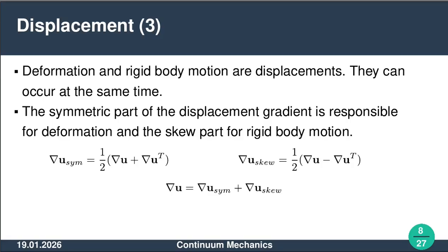The aim of continuum mechanics is to develop constitutive equations about cause and effects of a body motion, about strain and stress, etc. And for that, we need to tell rigid body motion from deformations. Fortunately, the displacement gradient matrix is square. The displacement gradient tensor is a square tensor.